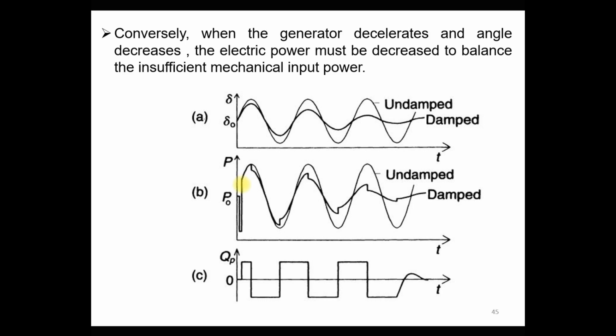By reactive power compensation you can maintain the system bus voltage in such a way that you can increase the active power transmission. So during the acceleration of the oscillation, the compensating device, it may be a STATCOM or SVC, injects reactive power into the system and that increases the active power transmission. Clear? That is during the acceleration point.